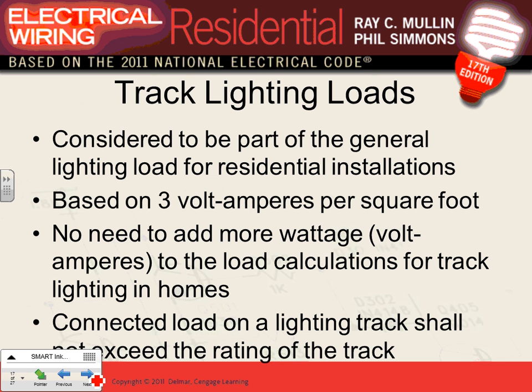Keep forgetting. Yes. So here's the square feet, guys. Your 3 volt-amps per square foot. Can I get you just to understand, based on the code, the track light is included in this 3 volt-amps.